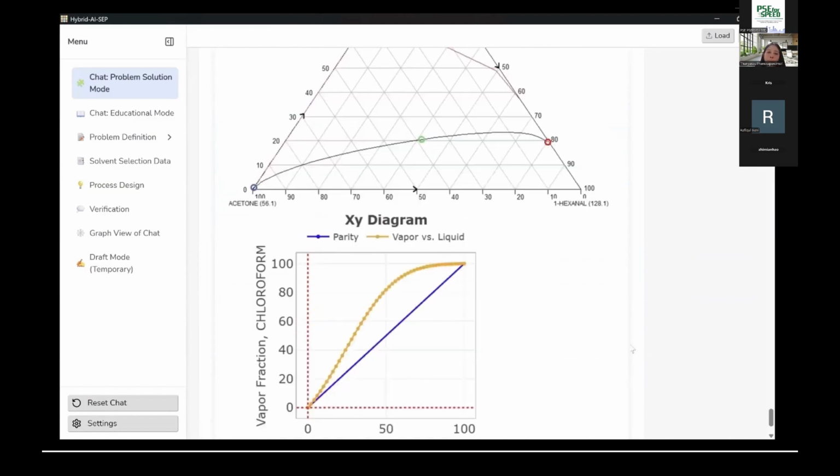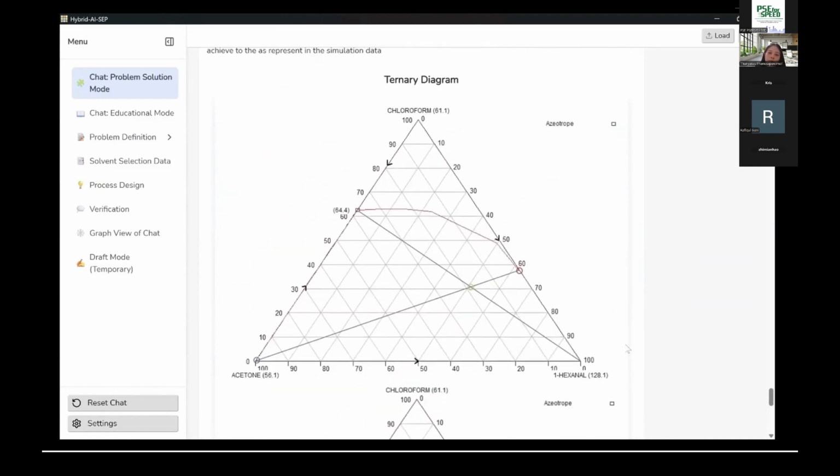This confirms that the design objectives we stated at the beginning have been successfully achieved. From the ternary VLE diagram, we can also see the feasibility of the desired separation. We need a solvent that does not cause a liquid phase split, has good affinity for chloroform and also high selectivity for chloroform. The solvent does not form an azeotrope with either acetone or chloroform. The only negative side is that in the solvent recovery column, some chloroform will exit with the solvent.